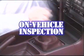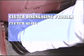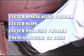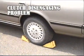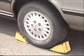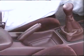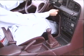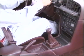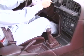Here are general explanations of 4 problems found in on-vehicle inspection: clutch disengaging problem, clutch slips, clutch engaging problem, and unusual sounds or noise. First, put stoppers under the wheels. Fully apply the parking brake. Depress the clutch pedal and start the engine. Confirm that the shift lever is in the neutral position and release the clutch pedal.